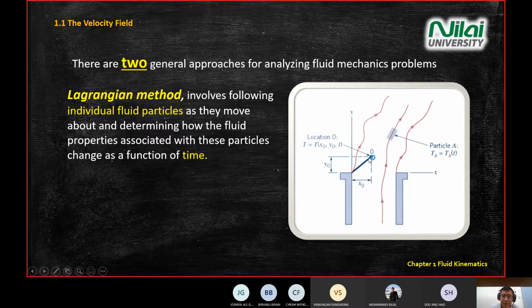In the Eulerian method, again, you are at a stationary position, and you measure the flow like you normally do a measurement. And in the Lagrangian method, you follow, like doing tagging. You have one sensor mounted on one of the particles, and you follow what happens to that individual particle. Lagrangian focuses on individual particles. However, Eulerian focuses on space and time. You do not move, you just stand there and measure what happens to the environment.